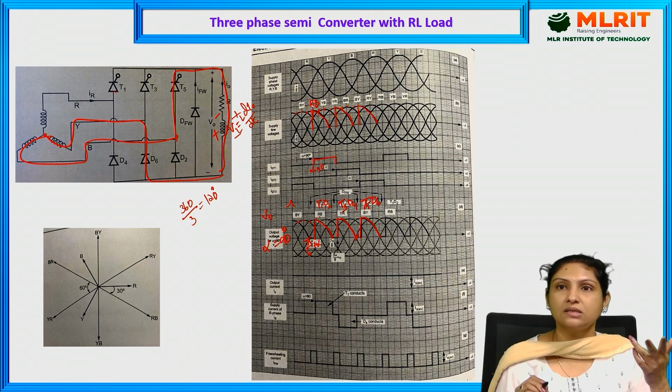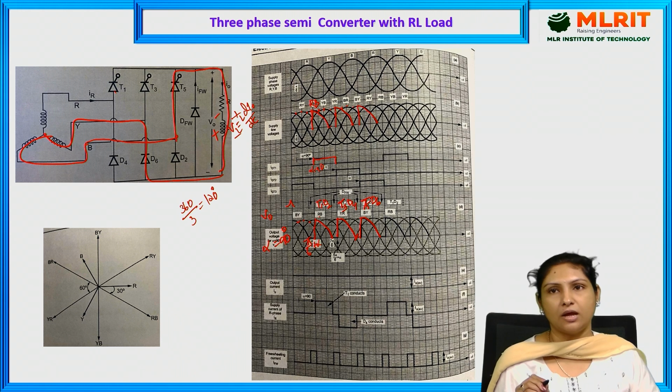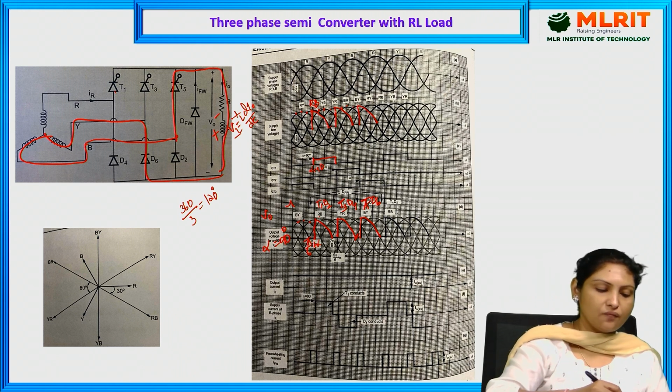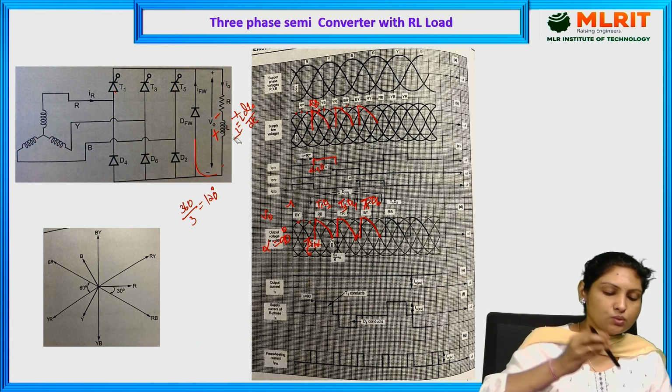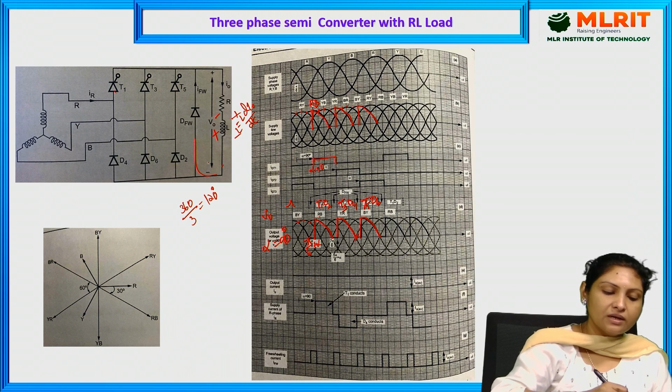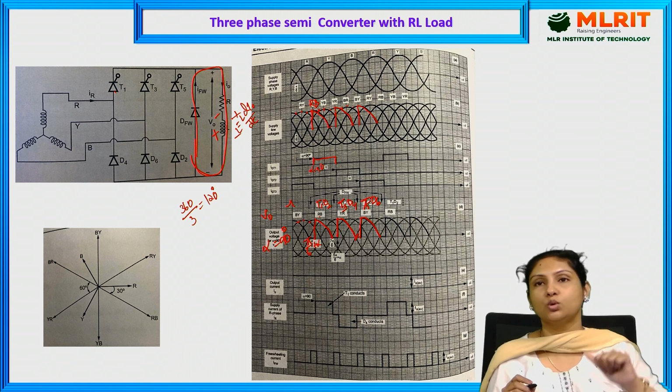That is the reason, according to Lenz's law, it reverses its polarities, because of which, compared to these two devices, the freewheeling diode will be more forward biased than the other two devices which were conducting. The energy stored in the inductor will be fed back to the load.